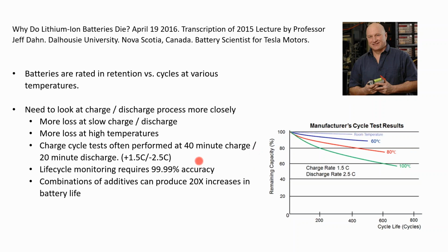With that in mind, how do you give a battery a 10-year or 30-year life, given that even some of these battery companies are only a couple years old? Well, what they do is rapid cycle the battery. So they'll charge it over a 40-minute iteration and discharge it over a 20-minute iteration and use that to estimate its useful life.